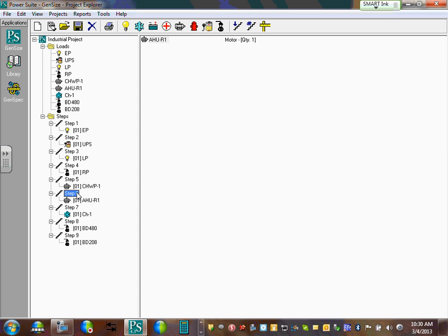That's your gen size. When you're done, here's what you need to do. Say you came up with 1250. You're going to take it and type into Revit 1250 on the generator kW, and you need to go back and size the feeders based on 1250 for the generator. How do we size it for a generator? Do you guys remember the sheet that I gave you, how to size the feeders and overcurrent protection device? Basically 1.25. You're going to resize the feeders after you come up with the size of a generator.